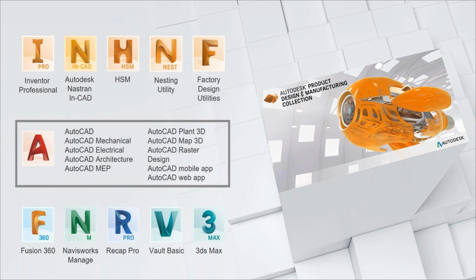So again, that eliminates the need for maybe some sort of issues with data translation. Oftentimes what we see is that some of the CAM tools can only export or import certain file types. Again, with Inventor Professional, you're going to be modeling and programming the toolpaths all in the same tool, essentially. Yep, so you don't need to worry about having to step out files. That term is used a lot in these CAM workflows, when you're exporting to STEP from your CAD tool so that you can open it in something like Mastercam or GibbsCAM, if it doesn't automatically detect the file translation from native Inventor or SOLIDWORKS data. Right, exactly.